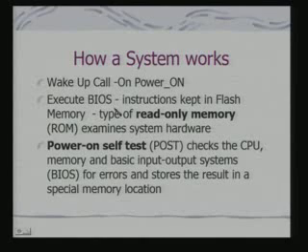And this memory initializes and examines the system hardware. In most of these embedded systems, there is a power on self-test block, which checks the hardware when it boots up. Typically, a memory test is performed in order to ensure that the embedded system does not give rise to an unsafe state or an erroneous situation because of a hardware fault. So if it detects a hardware fault, it would abort.